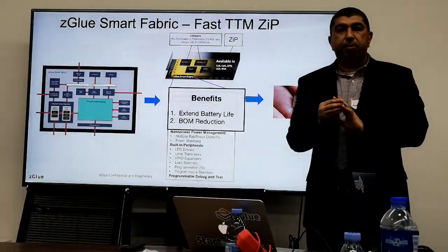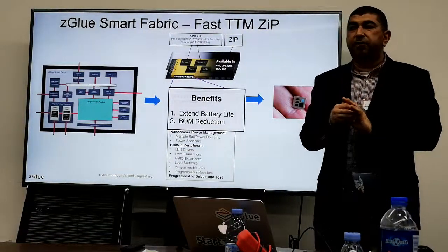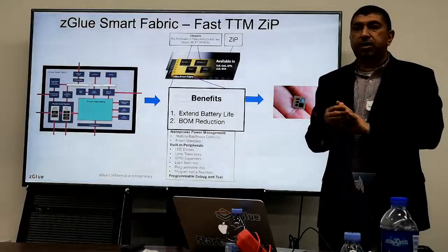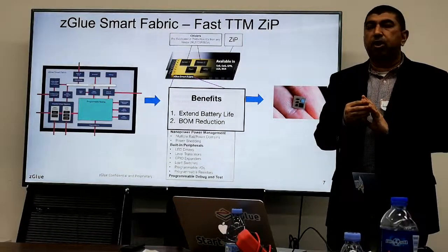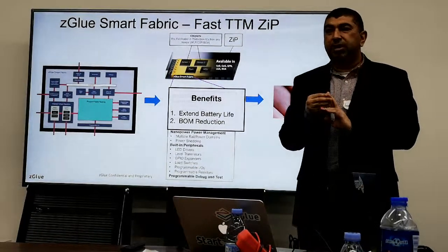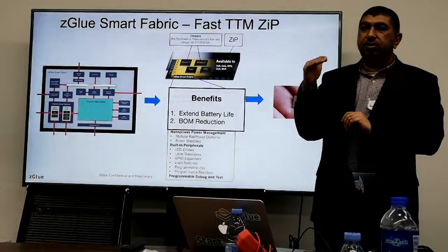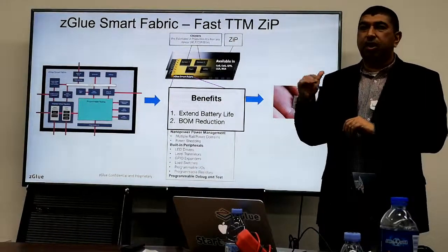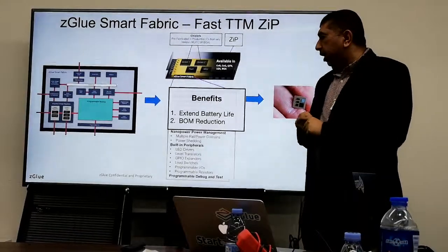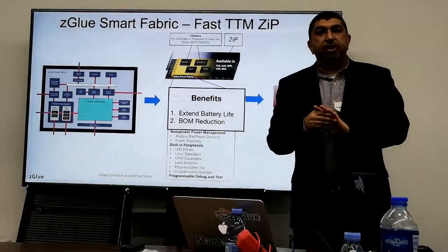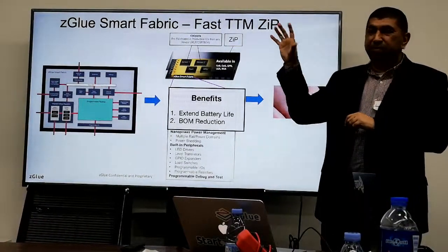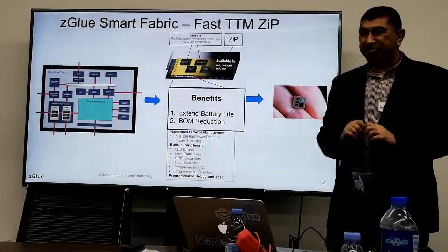If you look at the microprocessors, those guys have developed lots of interesting techniques. There's one called dynamic voltage frequency scaling, where they can change the voltage and frequency of the microprocessor on the fly. And they have another one called power gating, where whatever they don't use, they just shut it off, right?